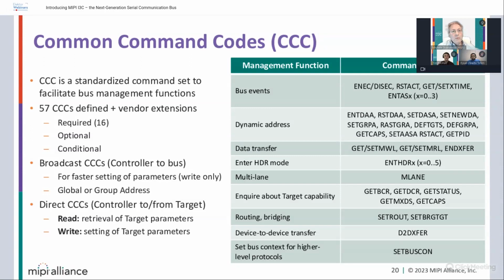There is a pattern called target reset. What should a target do when it receives this target reset? Do a full reset, or only of the peripheral, and so on. There is the delay time, and a whole number of parameters entering into some bus states, like idle mode to save energy. Quite a few command codes are actually reserved for what's called dynamic address management.